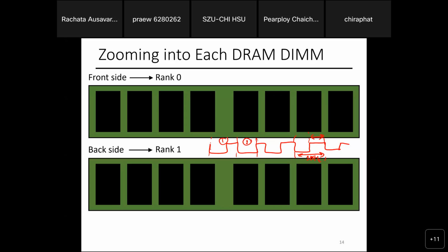By the way, it says 3200 megahertz. That's actually 1.6 gigahertz. You got the idea how they use that number. Yes, it does sound like a scam. But it behaves as if it works with a 3.2 gigahertz clock. That's how slow DRAM can be compared to the CPU. You can't clock that fast.